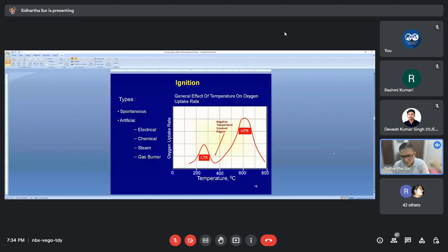So between 300 to 350, it is oxygen addition reactions. It is not complete combustion. No heat is liberated in this small hill portion. But the reactions go through a valley and enter the Mount Everest, the big peak. Here, entire complete combustion takes place. Here, the temperature reaches 600 degrees C. In this portion, all the oxygen breaks the chain of the hydrocarbon molecule into carbon dioxide and water.